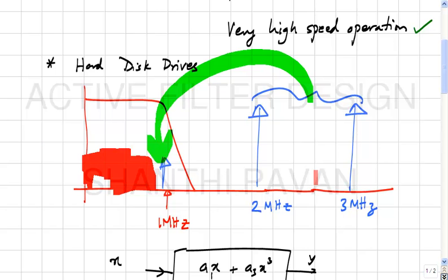All right. So as you can see, nonlinearities in the filter can be a serious problem, right. And please note that in this case the desired signal is very small. So one might think that, hey, anyway the signals which are out of band are going to get eliminated, so why should I bother about linearity in the filter.